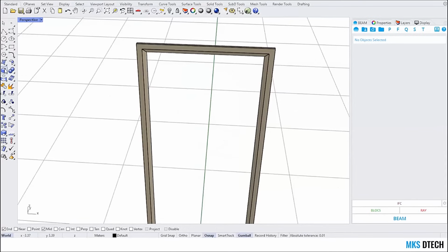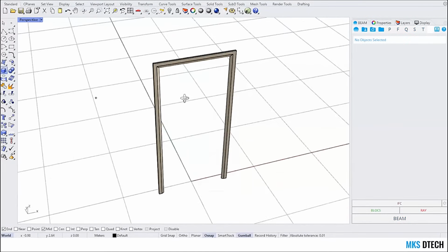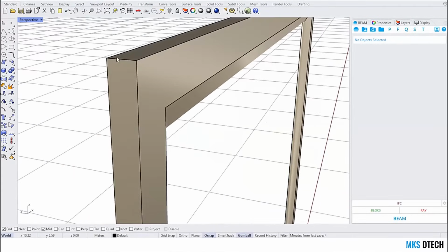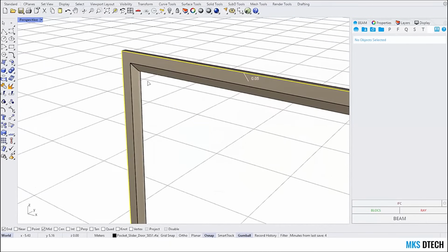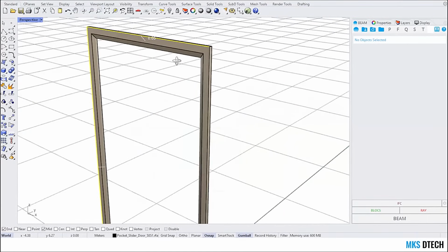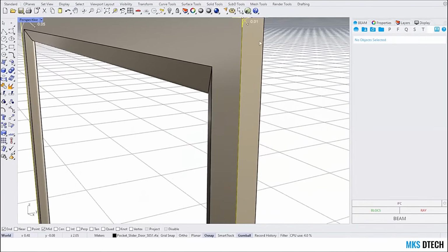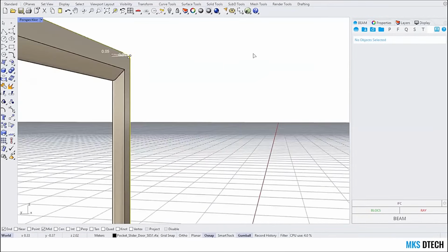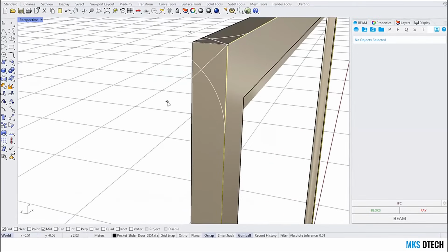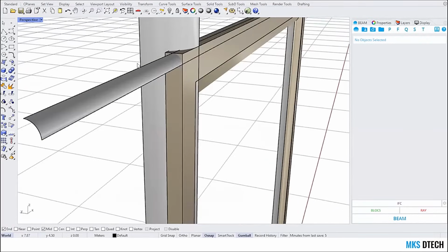If I need to add some object, let's say, maybe I want to fillet this. I want to use fillet edge, which is a tool that we really need in Dynamo. So let's say the radius, let's put 0.05. Okay, so maybe I want to fillet this, but my Rhino doesn't behave. It's a bit too much. Let's make it 0.01. Maybe too much.